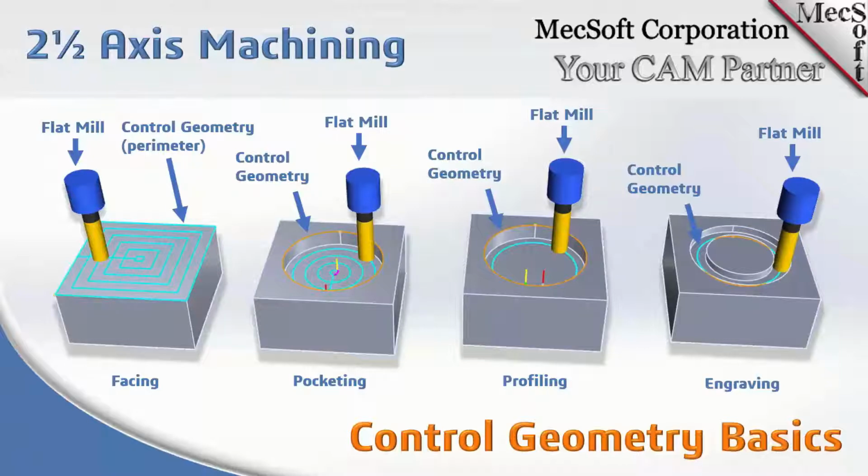And then the engraving operation on the right, I showed a round slot. You don't have to have any geometry other than a curve for that tool to follow. I just showed a slot to give a representation of cutting around that control geometry. In this simplified case, it's just creating a rounded slot.